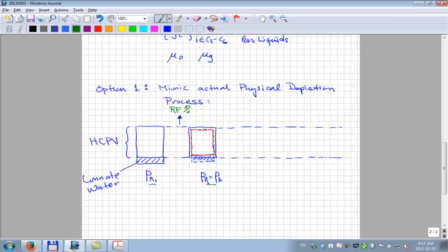If it's a highly undersaturated reservoir, like Crystal. Okay? So going from the reservoir pressure to the saturation pressure, you can produce a lot of oil. And that recovery is essentially given by the total compressibility times the pressure drop between initial pressure and saturation pressure.